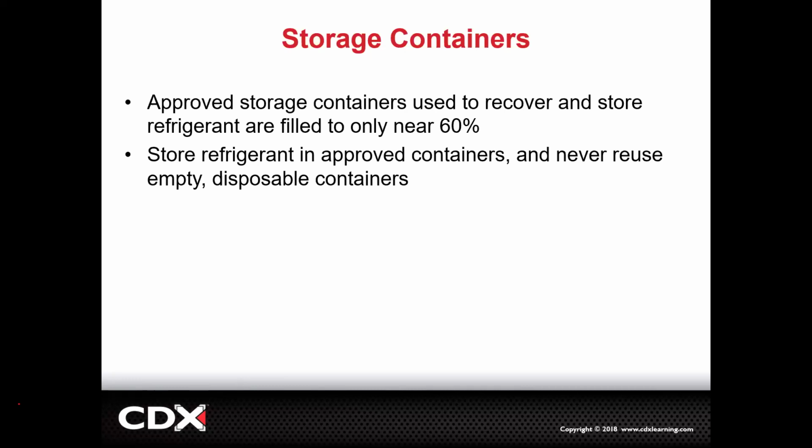Right. So the thing is, if you were to discharge into your own tank, because let's say you go into mobile HVAC, you need to know that if it's a 10-pound tank, you can only really fill it to 6.